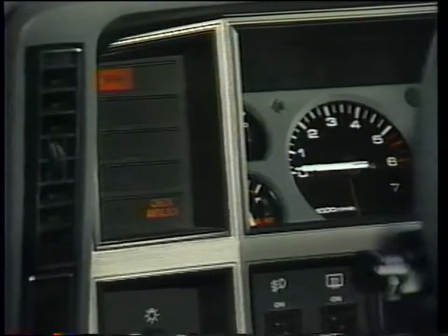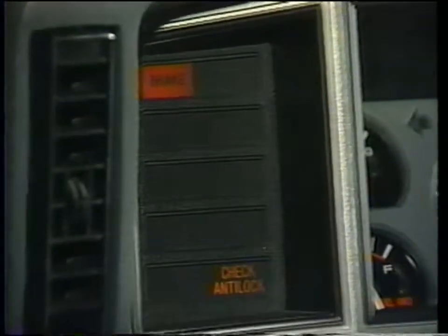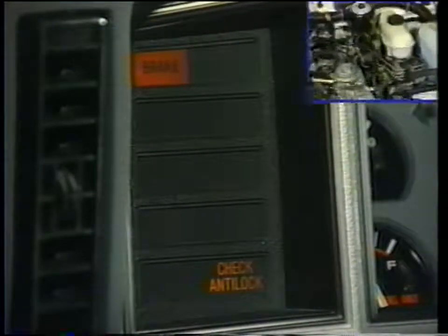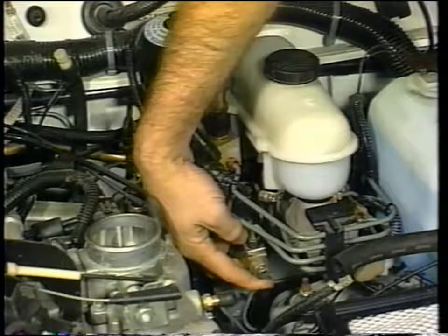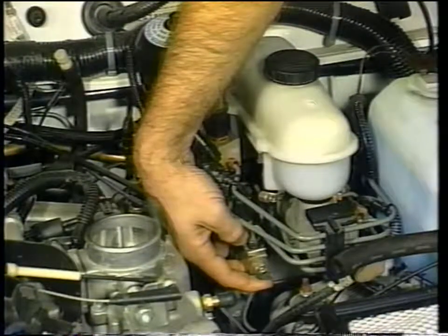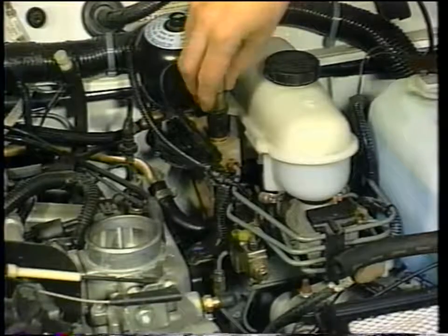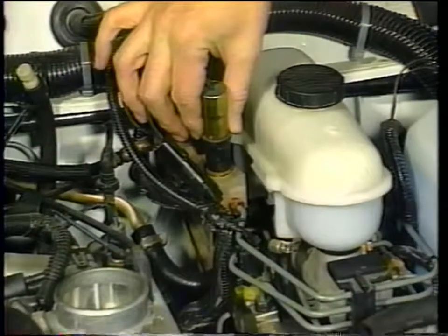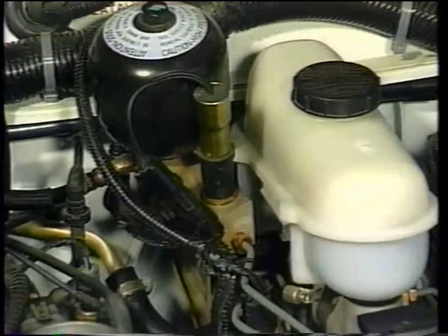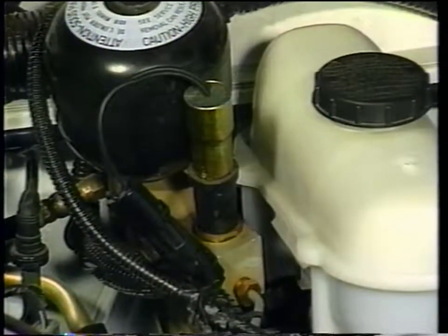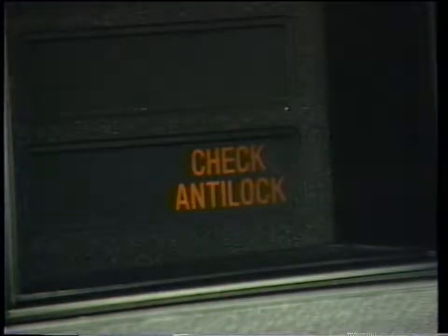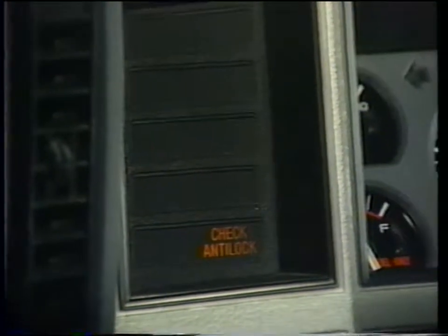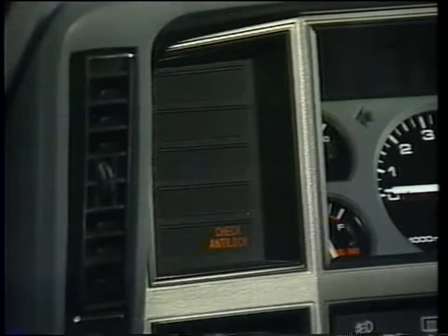The controller then illuminates both the red brake warning light and the yellow ABS warning light and disables the ABS system. There's also a brake proportioning valve and switch, which are similar to other proportioning valves, and an accumulator low pressure switch for signaling the controller if accumulator pressure is lost. The accumulator switch is also a one-terminal self-grounding switch that stays closed during normal operation. If pressure in the accumulator drops below 1050 psi, the switch opens and the controller illuminates the yellow ABS light.